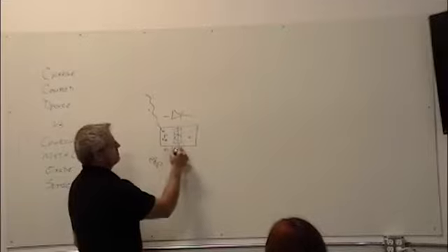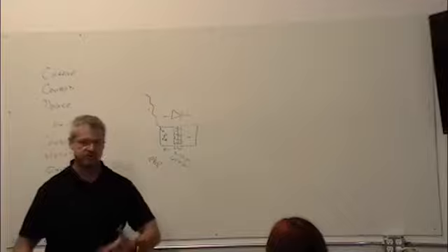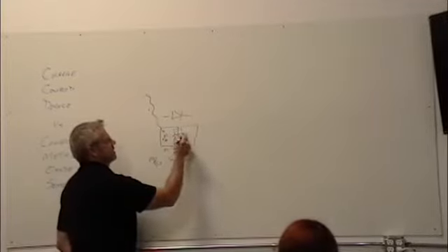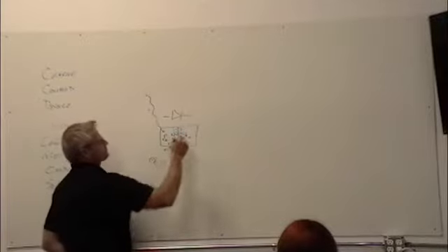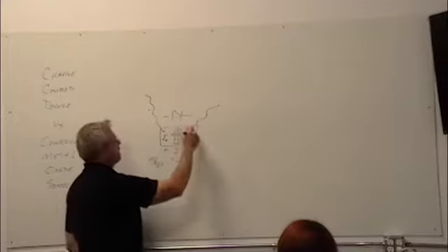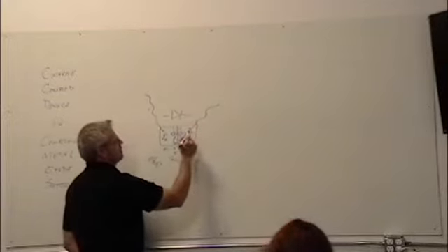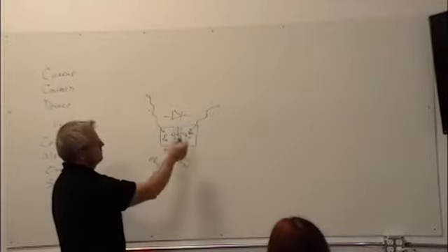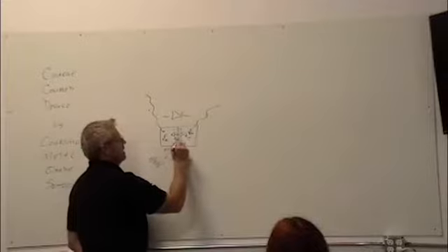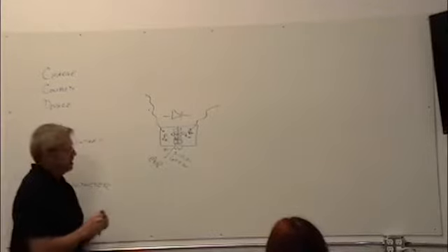Because there's an electric field between this N-type and this P-type, there's a bunch more electrons over here, and a bunch more holes over here. That draws a hole this way and an electron that way. So if I get a gamma ray, light, whatever, happening here, I get an EHP, and it recombines. But if it happens anywhere in that diffusion region, now a hole is